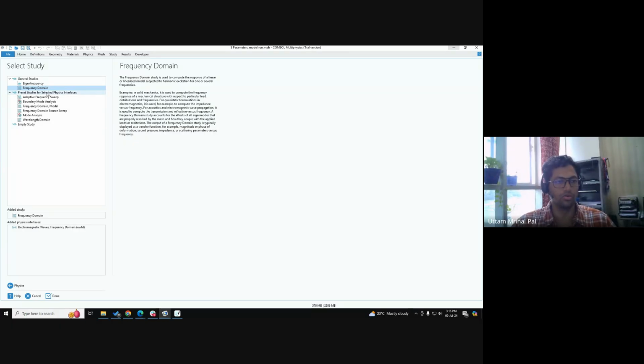You need to do more boundary mode analysis to figure out which mode we need to excite, but let us not add it right now. You can add it later as well. Let us choose frequency domain and click on done. Please select frequency domain study and click on done.